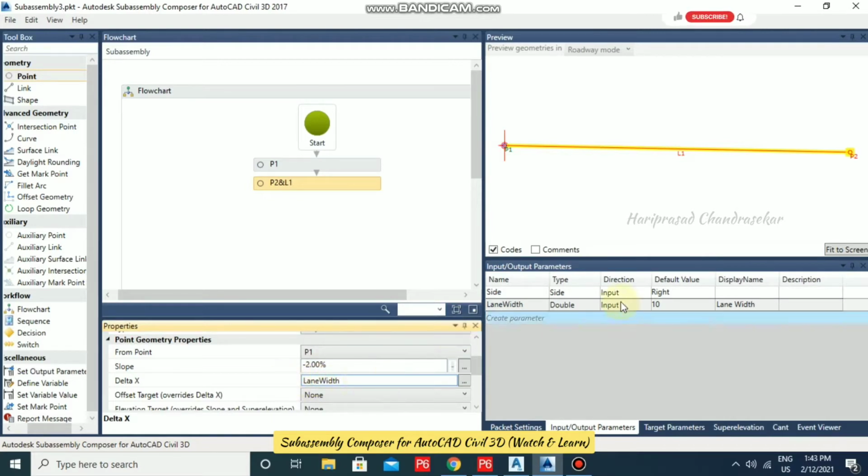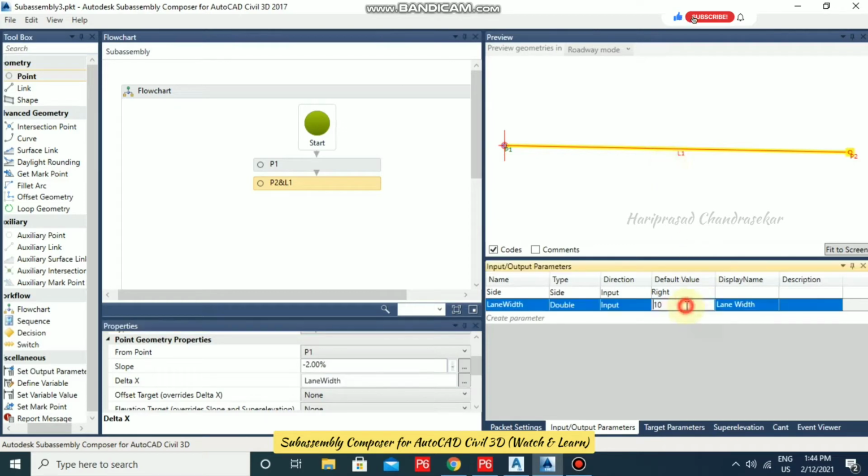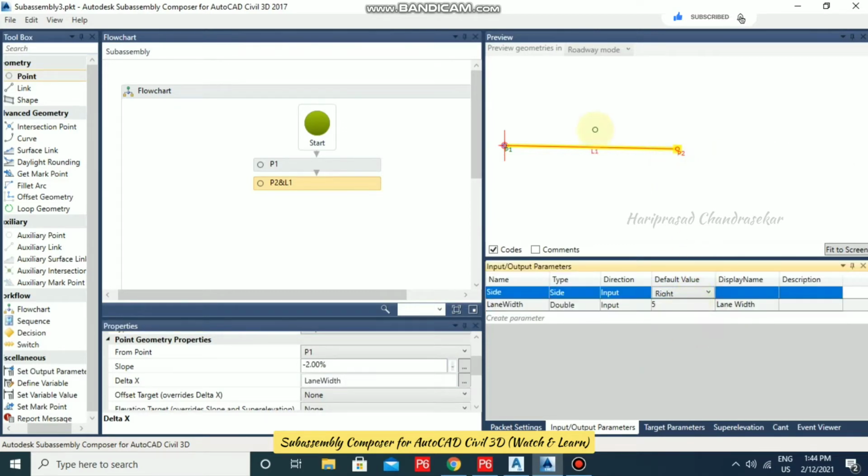See, now once you're changing this value, here it will be automatically updated. For example, I'm just putting 5 and you click outside. Can you see how it is getting updated? So this is why a parameter is useful, because we can't go with a single value as our project will be handling multiple values. So parameters could be very useful for us to work with.